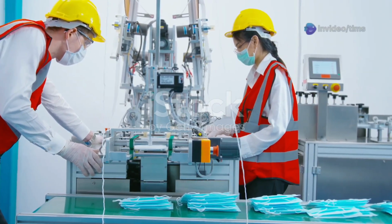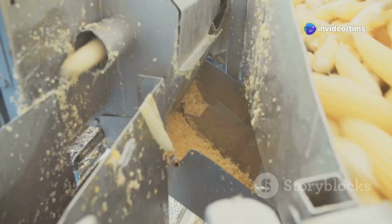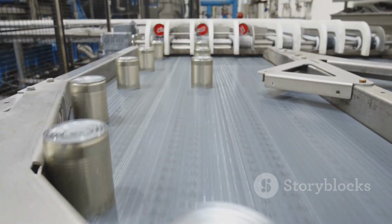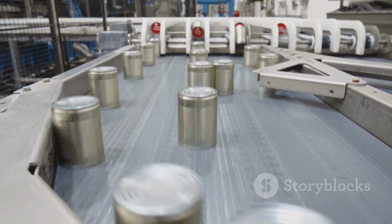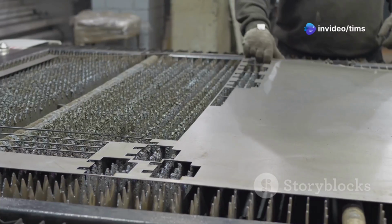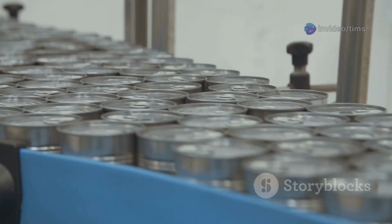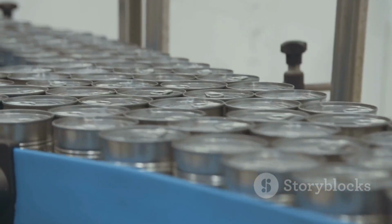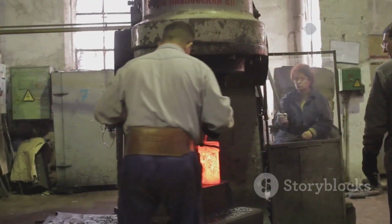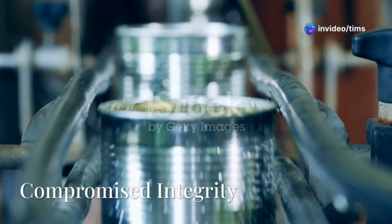Several factors can lead to misformed seams. One common cause is improper adjustment of the can seamer. This machine plays a crucial role. It needs regular maintenance and calibration. Another factor is the quality of the can bodies and ends. These components must meet strict specifications. Inconsistencies in metal thickness can also create problems. If the metal is too thick or too thin, it can affect seam formation. Environmental factors such as temperature and humidity can also influence the process. These variations can lead to inconsistencies.